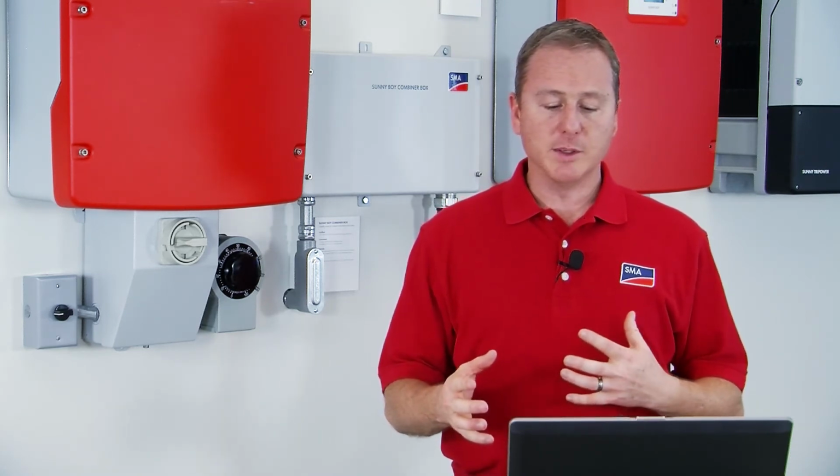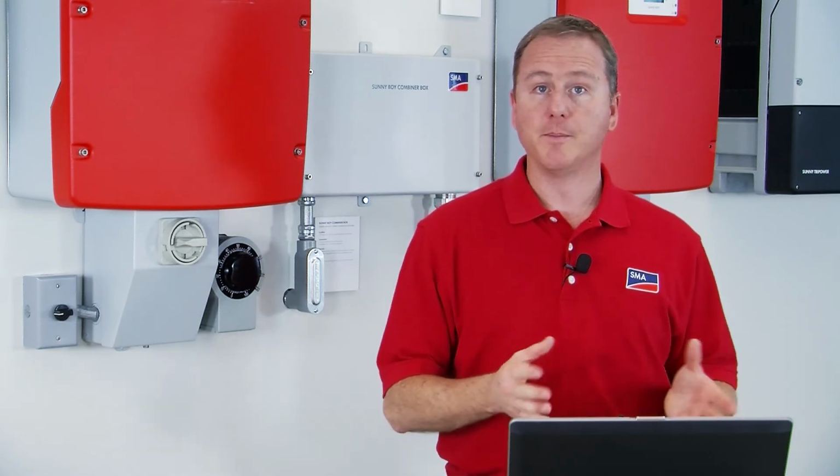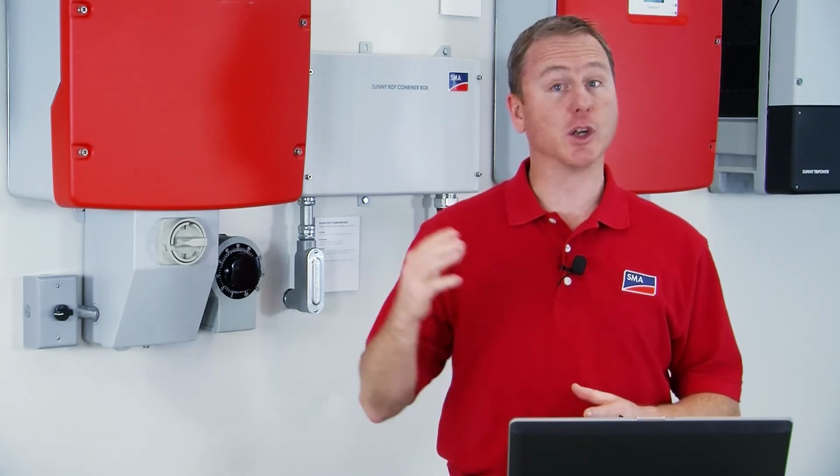Now, if you see a yellow exclamation point, then that means there's some kind of yield issue, which means your voltages are probably too low. If you see a red exclamation point, then red is bad. And what that tells you is that you are in an over voltage situation. So you're going to have to remove some modules off of one string.